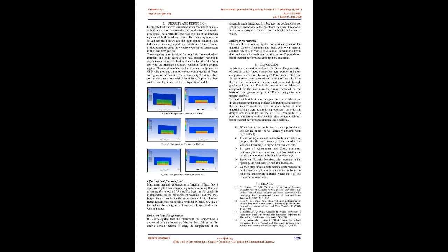An iterative process is carried out by repeated solving of the governing equations, thereby the errors converge to a bare minimum value, up to 5 decimal places for mass and momentum and up to 7 decimal places for energy, which means theoretically almost zero. Thus, the solutions obtained are more reliable with higher values of convergence. The number of elements used for discretizing the domain and the equations selected for fluid flow and conjugate heat transfer greatly influence the quality of the results achieved.